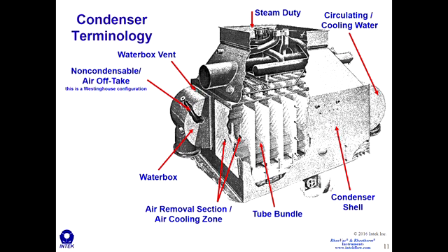So this water box vent here is for ensuring that the water boxes are full of water. Again, the water boxes can be under pressure or under vacuum. If under pressure, you would need a vent, or you would need a whole vacuum system with vacuum pumps to prime these boxes if they were under vacuum by design.